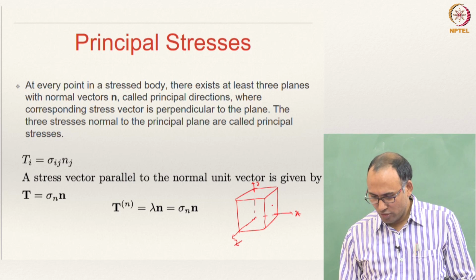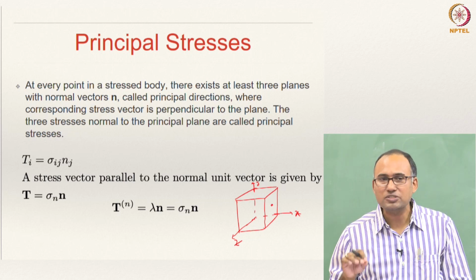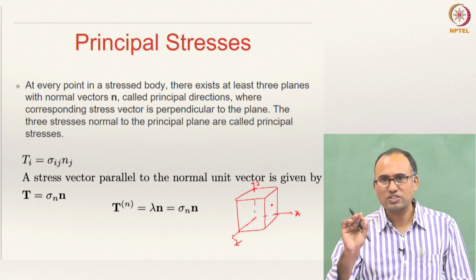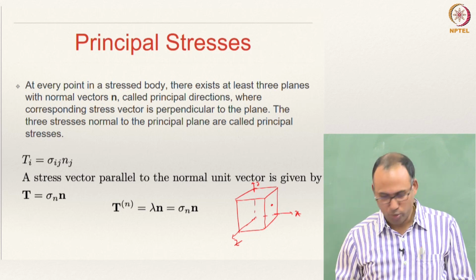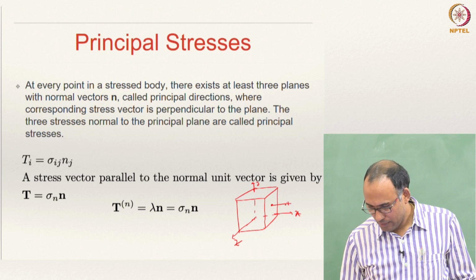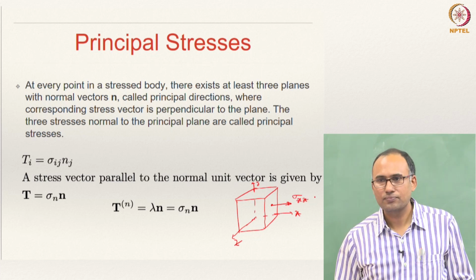Now, if I have to represent my stress state, it is a stress state at a point. This is an infinitesimal volume, that means it is pretty small. We are only showing it as an infinitesimal volume, but it is actually stress state at a point, represented by normal stress described as sigma xx.